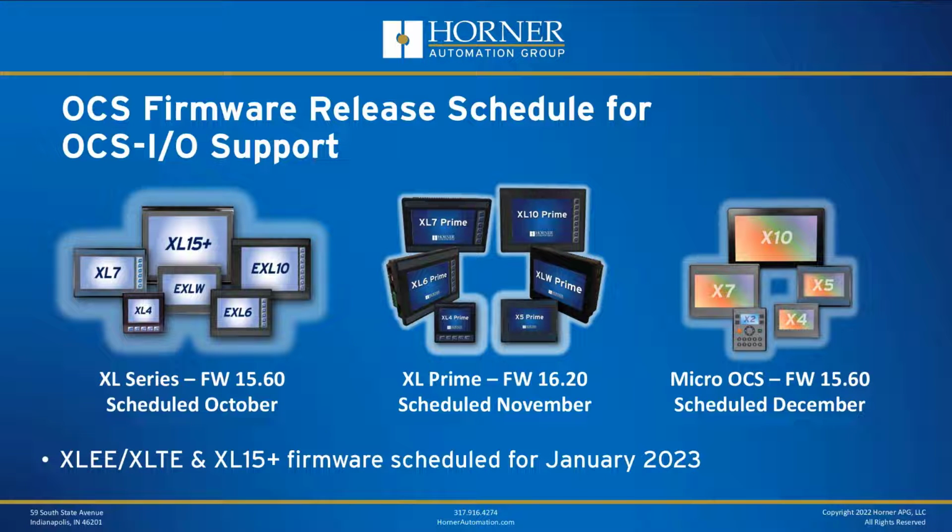And then you can very easily, just in your field terminal strip or with another accessory, convert from modular over to discrete CAN cable. Because so many customers use our I/O inside the same cabinet that their OCS is mounted in, we wanted to make sure we had the easiest possible approach for them in that scenario. But if you're going outside the control cabinet, generally the rule of thumb is that's the point you'd use traditional discrete CAN cabling.